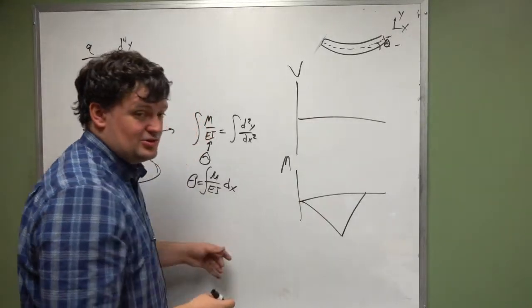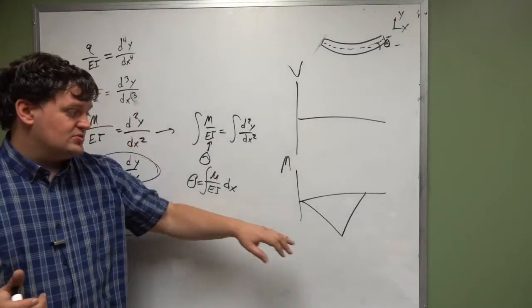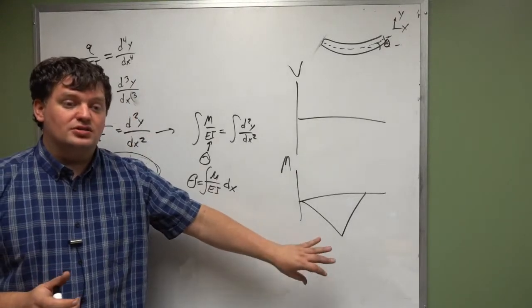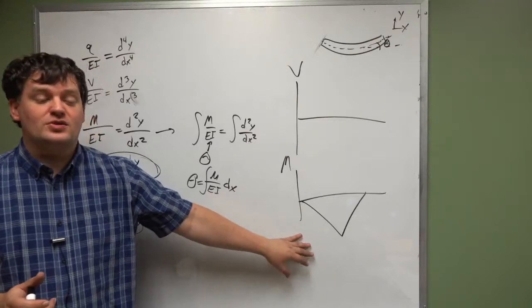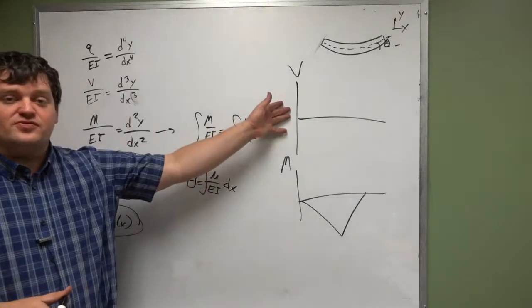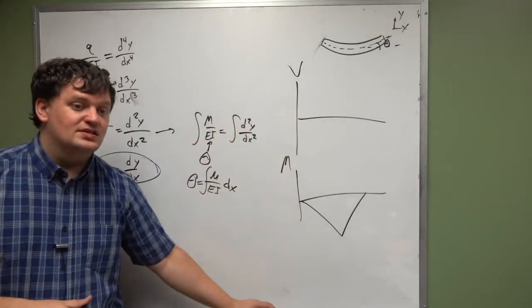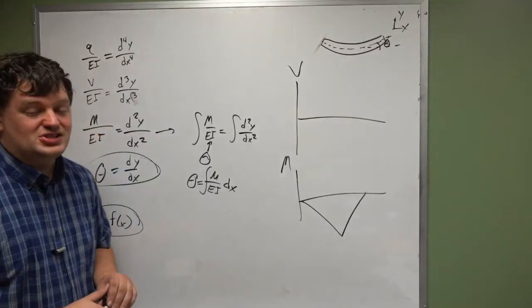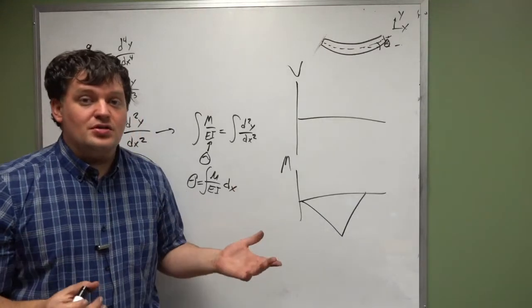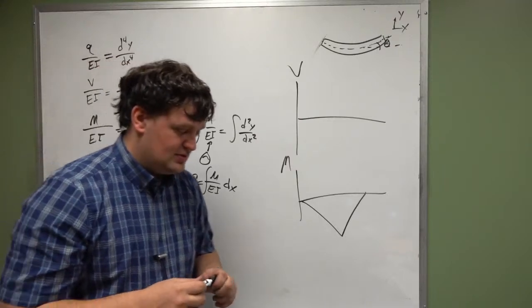And then the integral of that slope of the line is going to be the shape of the beam. So if you can do a second order integral over this equation, if you can get to the moment diagram and the shear force diagram, integrate this to get a moment diagram, integrate this twice, and you end up with the shape of the beam, you've done all the math you need to figure out what the shape actually looks like.